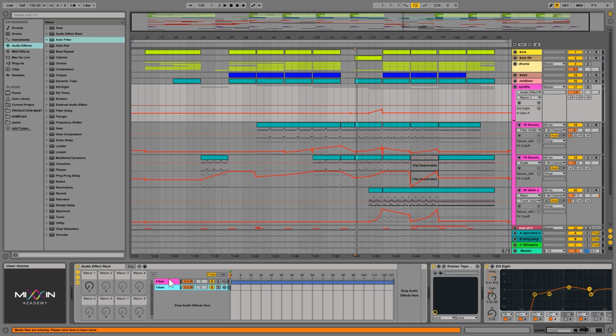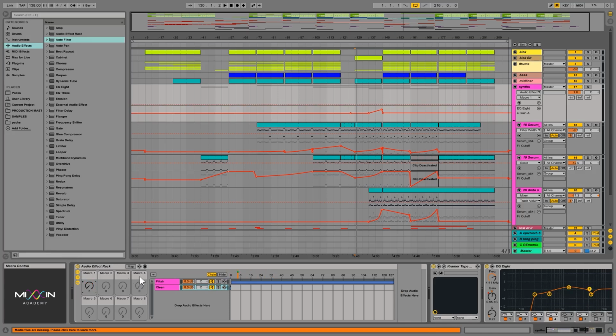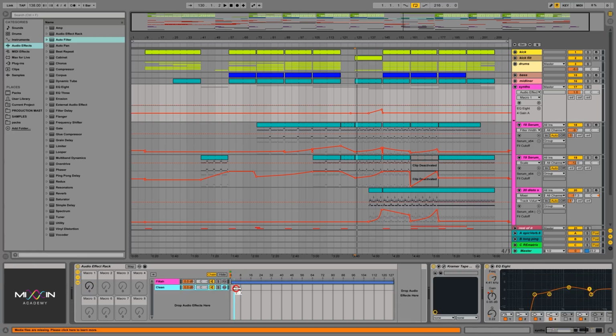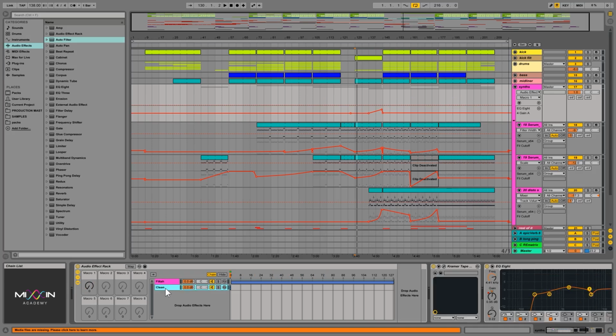So hence I have bypassed the filter altogether by connecting this macro to the actual chain selector and to this filter cutoff frequency. Of course, in this chain, I have made it so that this lowermost position goes through the clean and all the positions above that go through the filter. Let's try that out so I can show you that once I go up, it's going through the filter, and you'll see once I reach 0, it immediately goes through the clean.